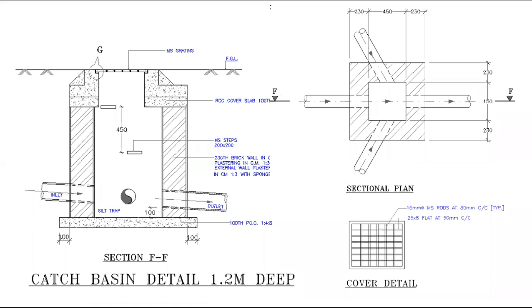Hello. Tell me. For a kitchen grease trap, is it possible to use it in any commercial project where a small kitchen is being used? Yes, if you have a commercial project, you have to provide a large grease trap based on the flow rate. If you have a small home, you can use a portable type of grease trap.